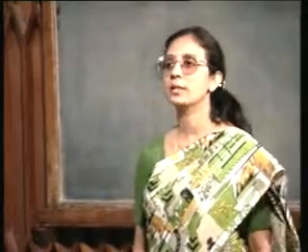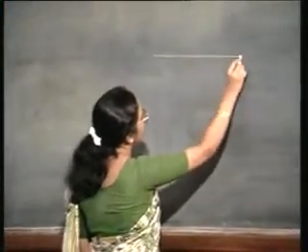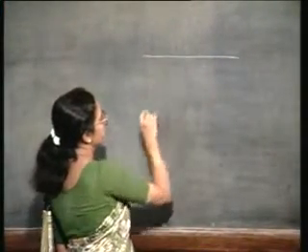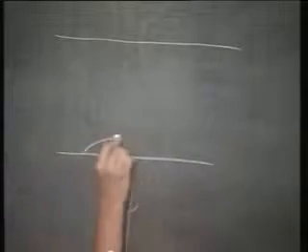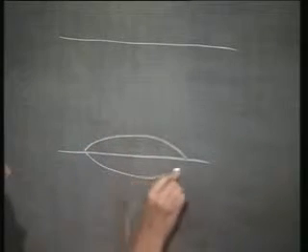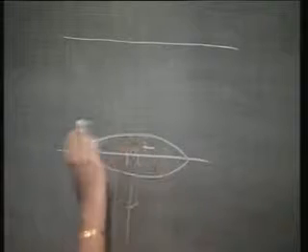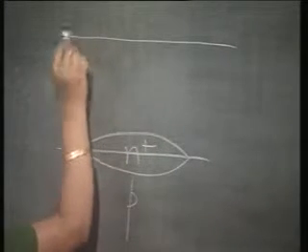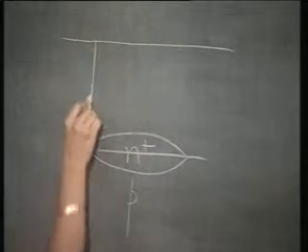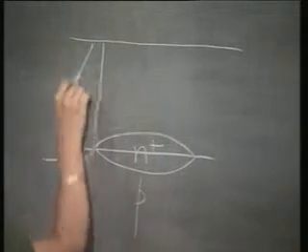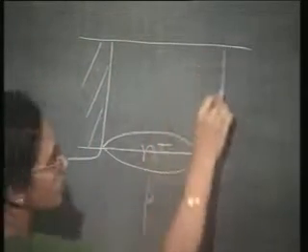Now, what do I mean by the active base? What I mean is simply this: I have this transistor, started from a p-type substrate, had the N plus buried layer, then I have the N epitaxial layer. I can have some kind of an isolation, either junction or oxide. Let us say I have oxide isolation here.